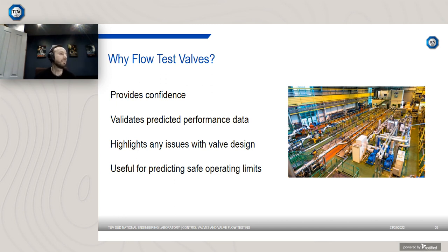The first thing it does is it provides confidence. If you independently verify that a valve CV is correct, it gives you confidence that when the valve is installed, it's going to meet its intended duty. We've tested a lot of valves that are intended for offshore service or even subsea service. Once the valve is installed, it's going to be very difficult to rectify any problems with the valve. So testing it before it's deployed can give you confidence, and it can actually save you a lot of money in the long run.